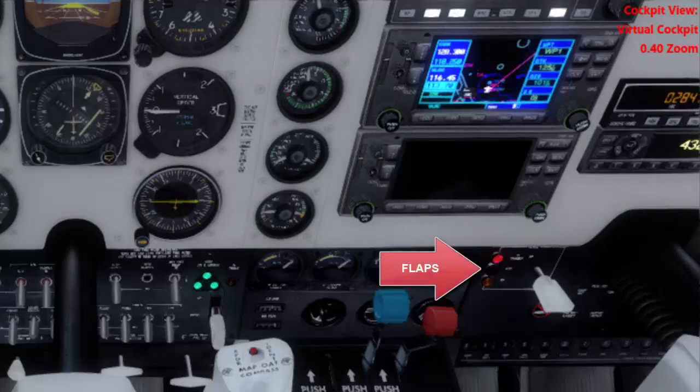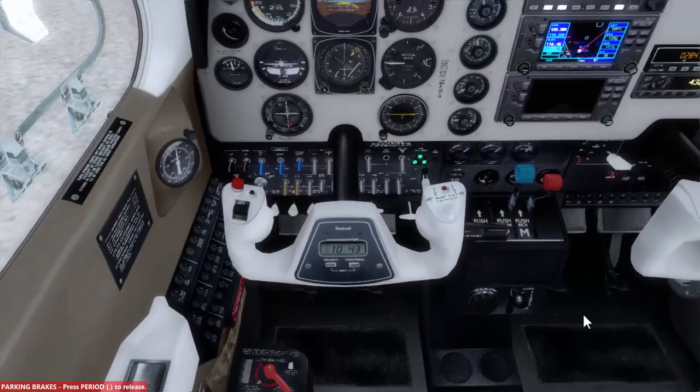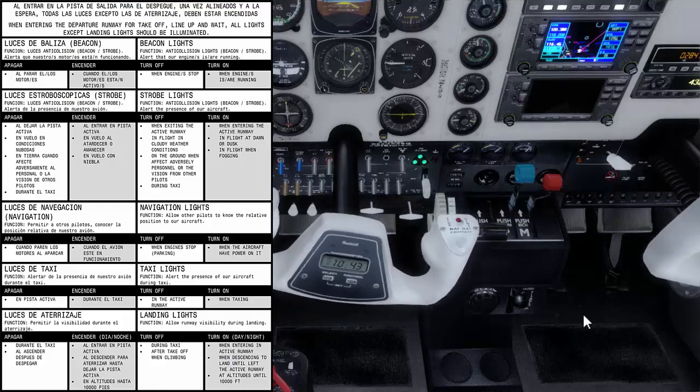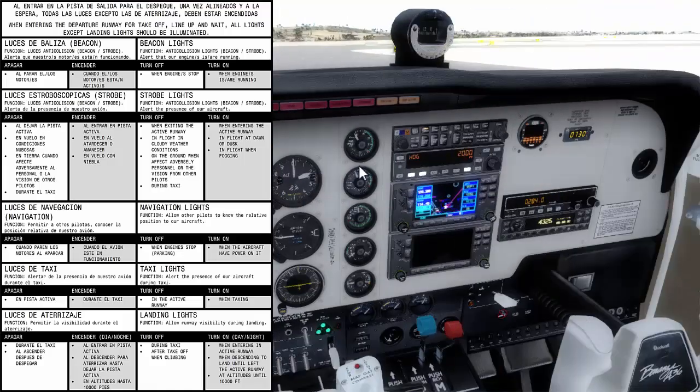So I'm testing also flaps. I'm the checklist. Don't tell me if I don't remember, but don't tell me to check out flaps, but I prefer to go beyond and also check flaps because I don't want to have any problem later on. And also again, I'm giving you the chart in which I'm showing you, I'm also testing the rudder. I'm giving you again the chart in which I'm telling you how to use the taxi lights, the strobe lights, the navigation lights, how to use all the lights in an aircraft, because we will have to configure again the lights before to take off.